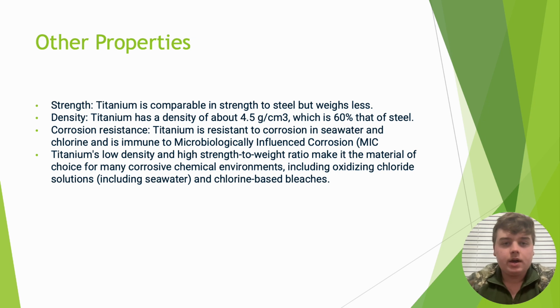Other properties. Strength. Titanium is comparable in strength to steel, but it weighs significantly less. Density. Titanium has a density of about 4.5, which is 60% of that of steel. Corrosion resistance. Titanium is resistant to corrosion in seawater and chlorine and is immune to microbiologically influenced corrosion. Titanium's low density and high strength to weight ratio make it the material of choice for many corrosive chemical environments, including oxidizing chloride solutions, including seawater, and chlorine-based bleaches.